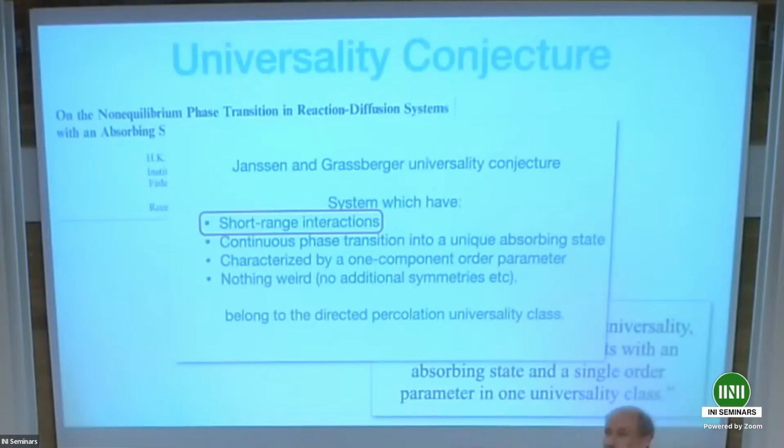So if you introduce something up here in your flow, it's not obvious the downstream won't notice it, because there's a global pressure field that is potentially going to be sensitive to that. So one of the reasons for having a model based on Navier-Stokes, which has this global coupling, is that then we can begin to think about that without having to do a full Navier-Stokes DNS. Okay, so that's one of the reasons I really want to have something that comes from the Navier-Stokes.